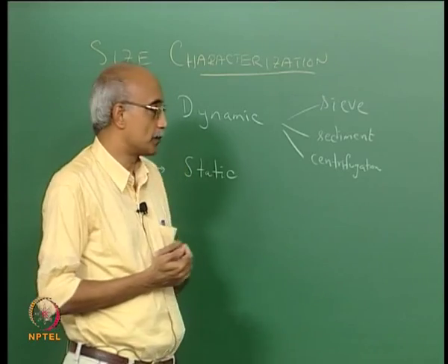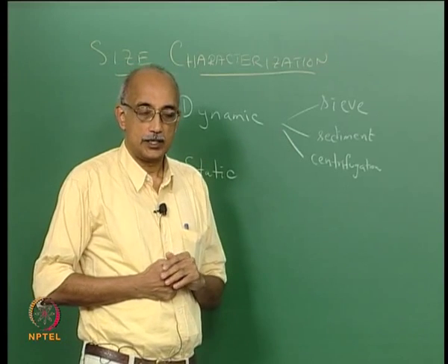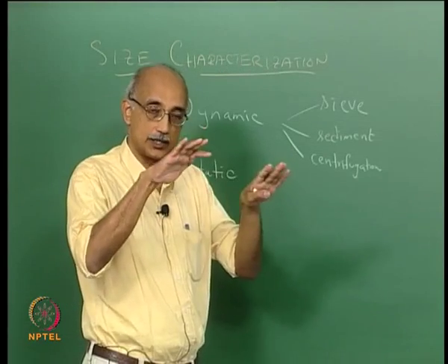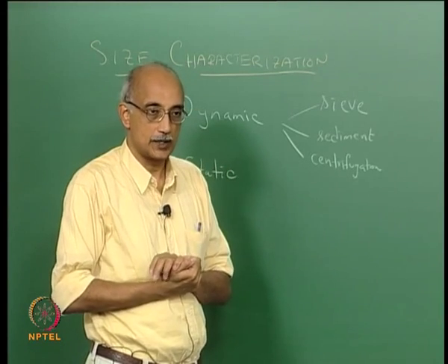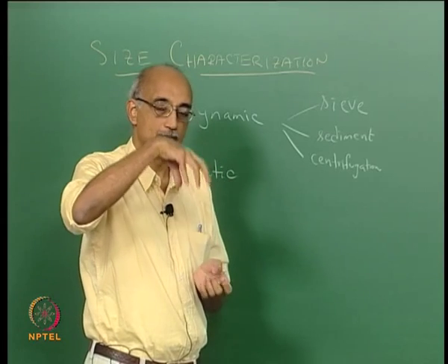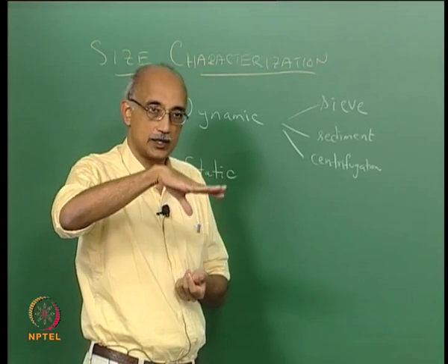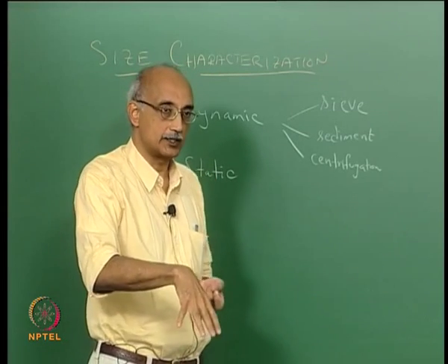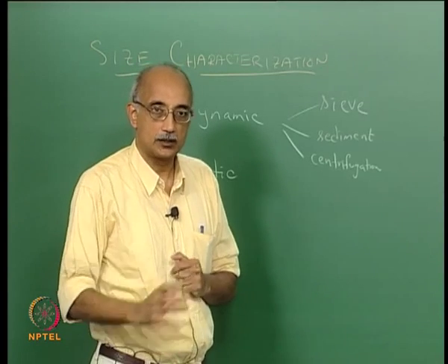So, what happens to the particles that you have put on the top sieve here? Well, the coarsest particles, which are coarser than the topmost sieve, stay at the topmost sieve, and then the finer ones drop through the mesh openings to the next pan below or the next sieve, and so they just make their way down until the finest particles make their way all the way down to the finest sieve and finally get collected.